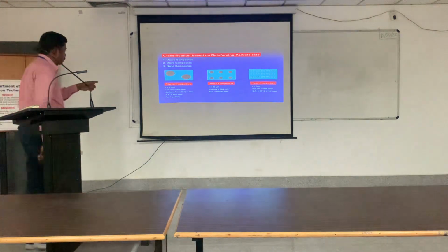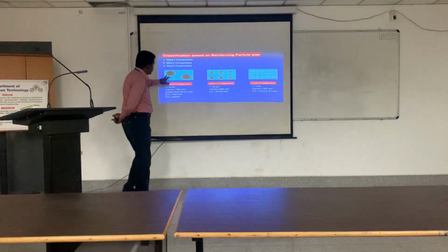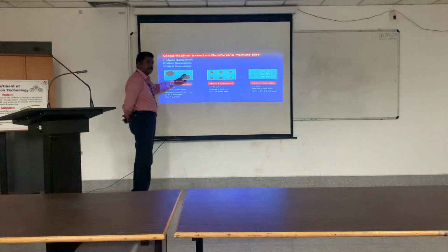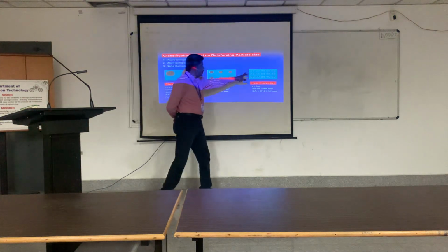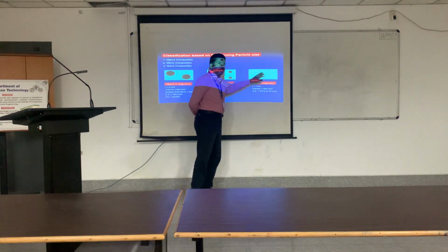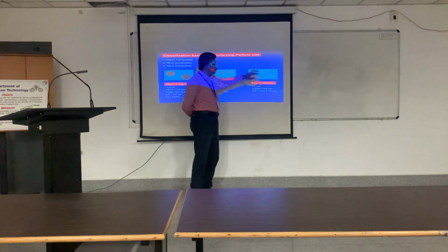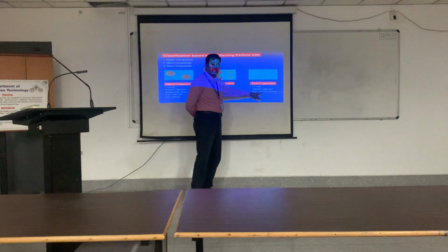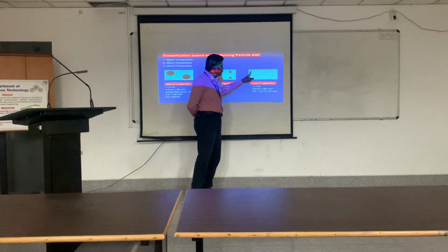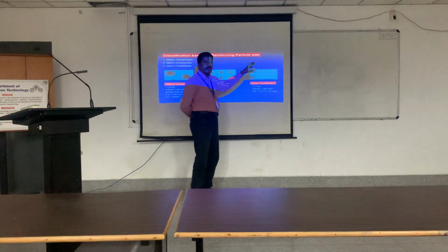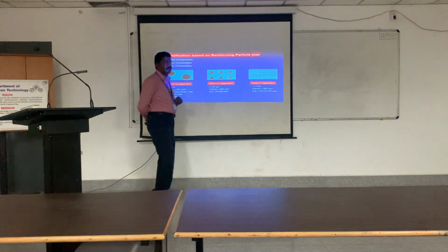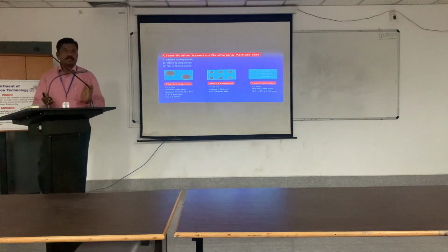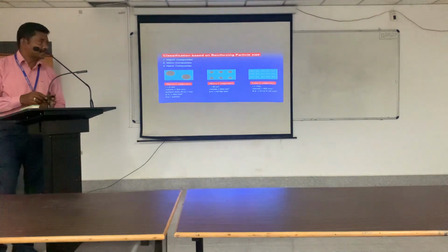Okay. So in the case of macro composites, the surface area of these two reinforcements will be lesser than the surface area of all the reinforcement in this plate. Okay. So here the surface area is higher, and accordingly, over all these surface areas you will get a higher amount of bonding strength. That is why nano composites will have higher strength compared to macro composites.